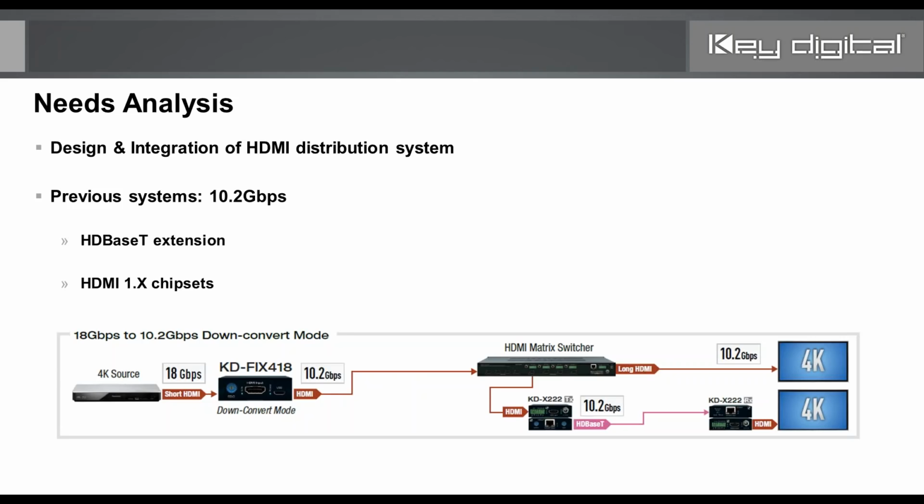You had audio return channel, which sounds great on paper for certain applications, but we saw many of the large manufacturers in the industry quickly turn that technology into a proprietary technology where it's only supported within the same brand as opposed to widely supported, because it does utilize CEC, the CEC chip or pin of HDMI, and so that became proprietary rather quickly.